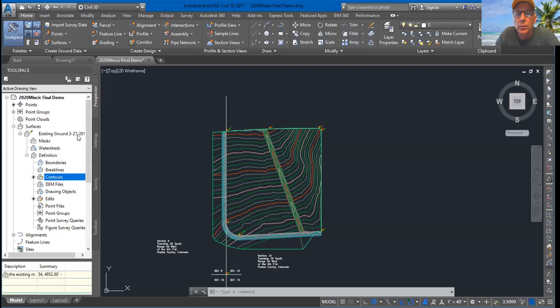I was careful not to grab the roadways or the outer boundary lines or any of the lot information. That roadway information does not have three-dimensional characteristics and is something you don't want to add into your contours. So therefore, I am confident that my contour surface is correct.